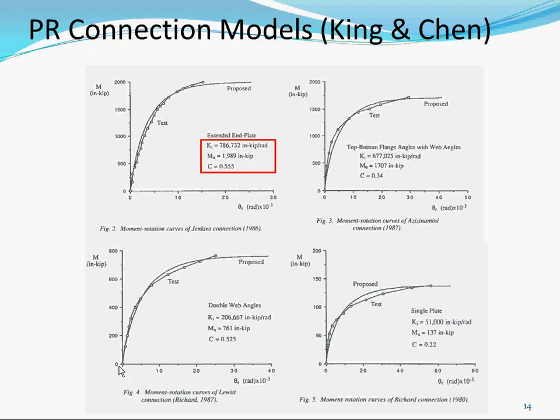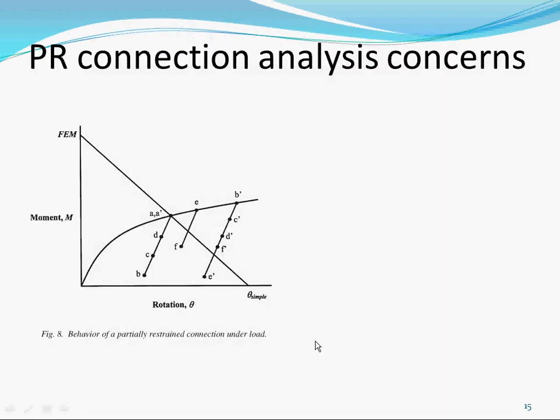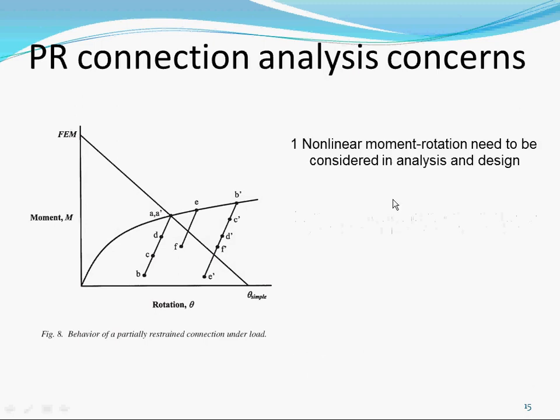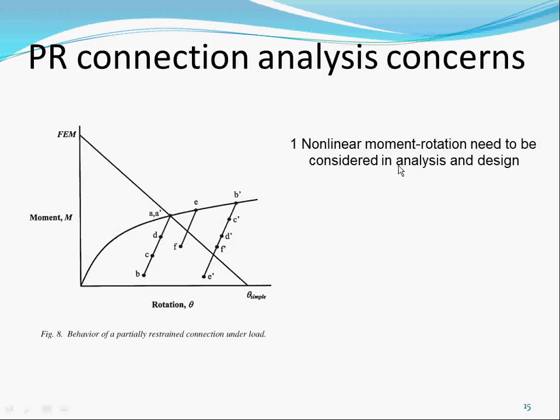You can see these are yielding very, very early. You blow it out, it's kind of starting to yield. Okay, so again, this is what we saw before. Nonlinear moment rotation is needed to consider in analysis and design for PR connections.